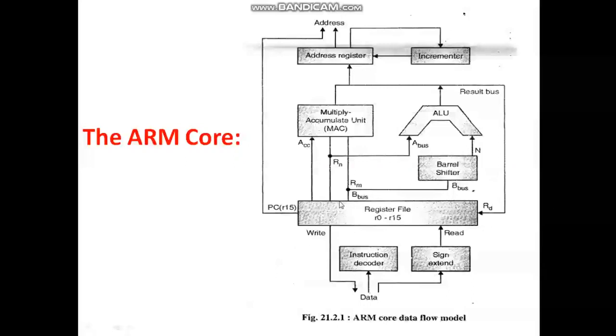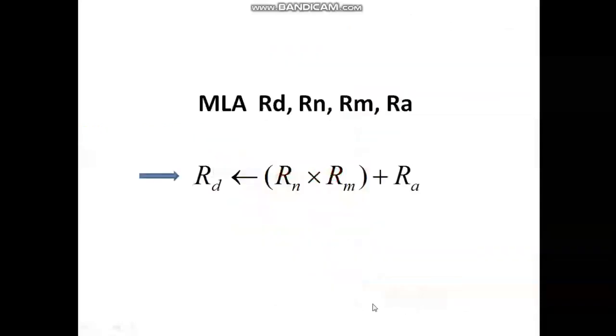When you want to store a result back to the memory, it is not a big problem, because the result is 32-bit and will be stored in the 32-bit register, but it may have a small value, maybe a 16-bit value or even an 8-bit value, and it may be a signed or unsigned number. In any case, when you want to copy that number into the memory, only the lower bits up to the sign bit should be loaded to the memory, and the value will remain unaffected.